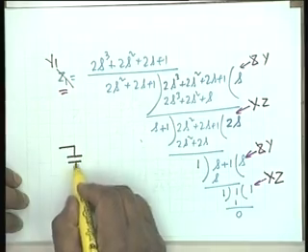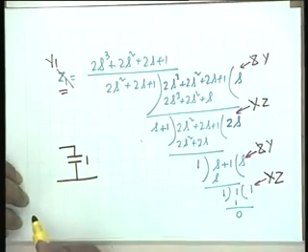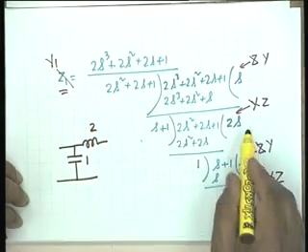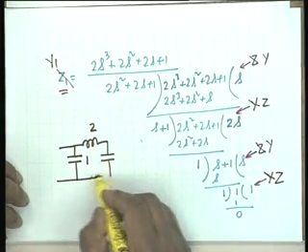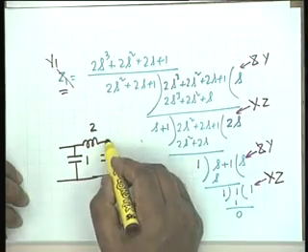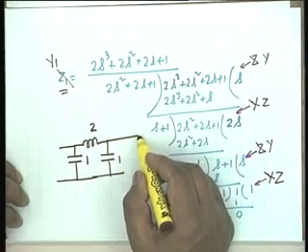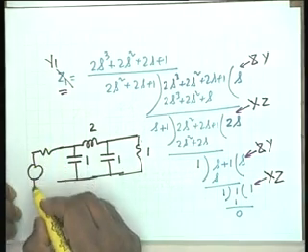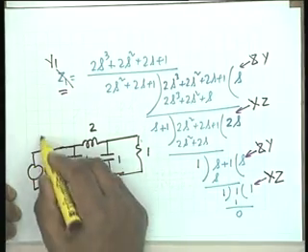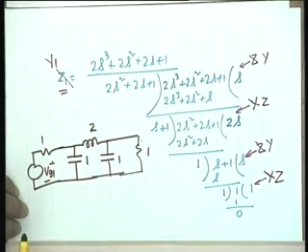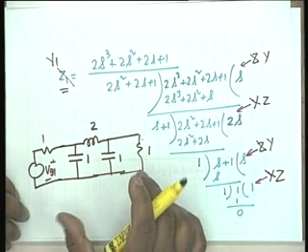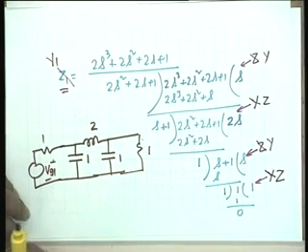value 1 farad because admittance is S. Then we have an inductor of value 2 Henry, twice S, then again a capacitor of value 1 farad, and finally an impedance of 1 ohm. So this is a perfectly valid alternative network to the first choice that we had made. Okay, we have found at least 2 networks which synthesize the given S21 j omega magnitude squared.